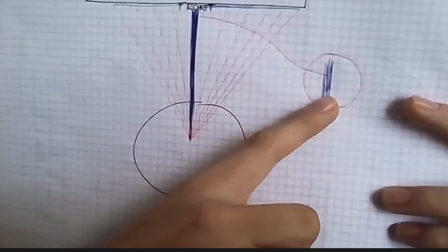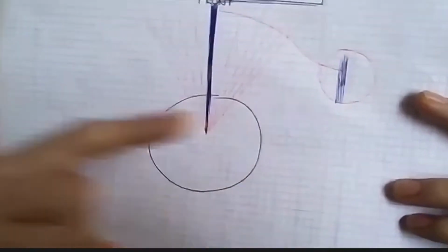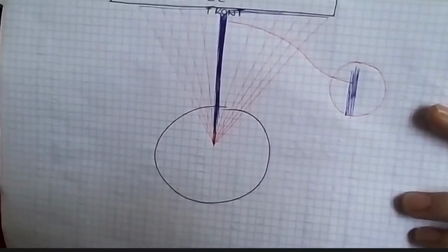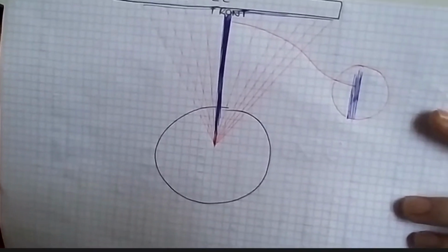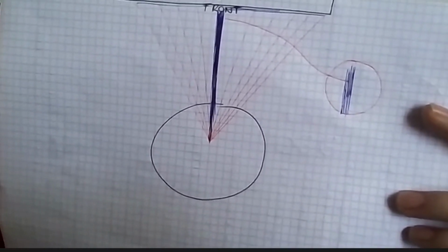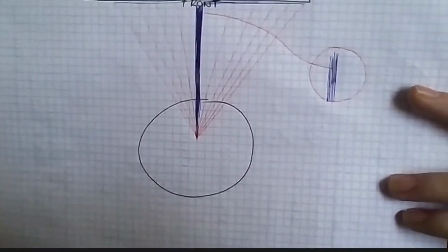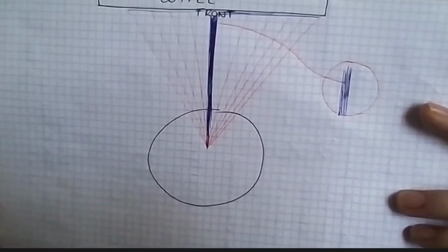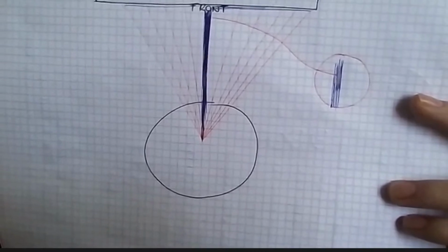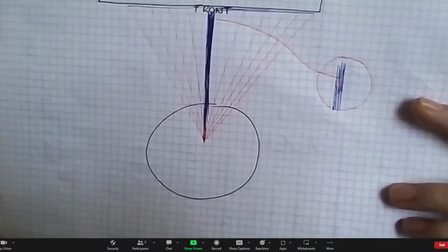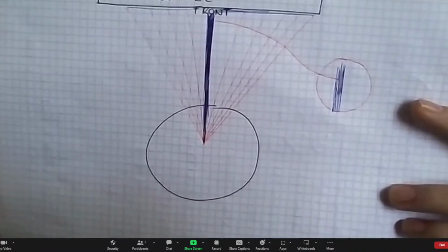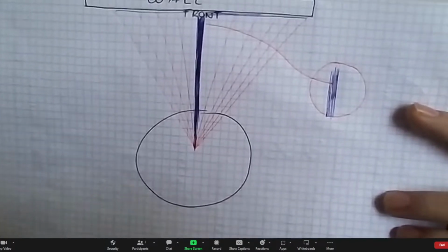But of course, here we have some noise normally with sensors. And I defined a threshold for the standard deviation in order to let me know that now all the projections are more or less the same, so we can assume that we are facing the wall. I understand. With the standard deviation.